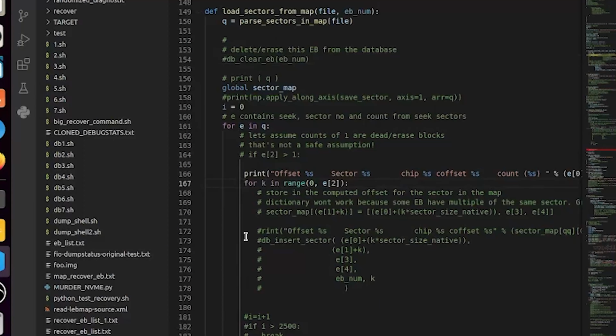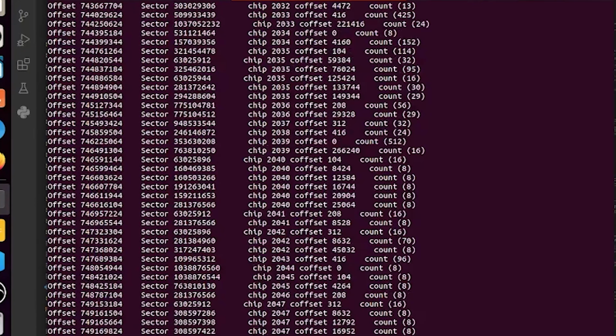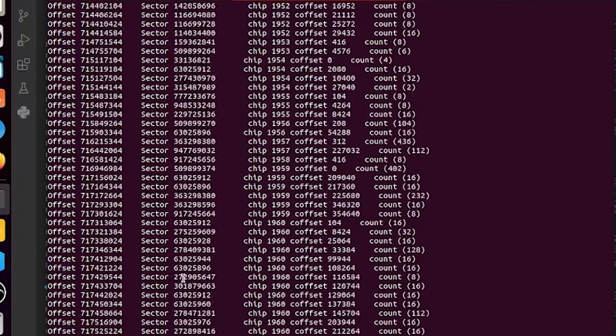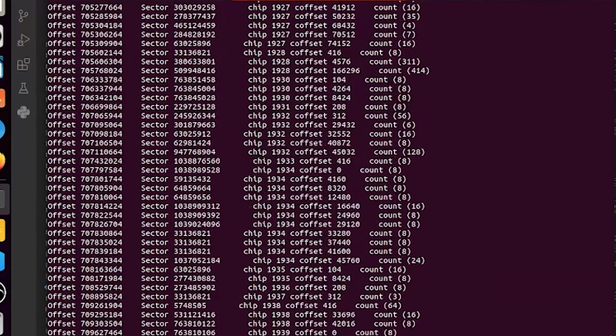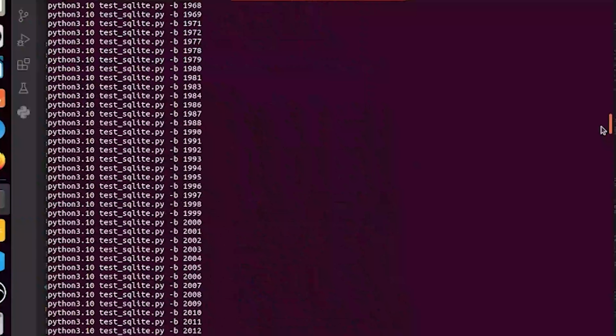So this is a perfectly working Fusion I/O drive. That's what we're talking about here. And I would write test patterns to it and then dump the NAND. And the test pattern was such that I knew where the beginning of the sector was and the end of the sector was and what the sector's individual number was. And so then I could look in the memory around those places once I found them for clues on which thing went where.